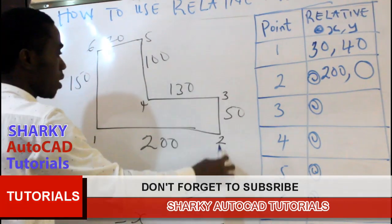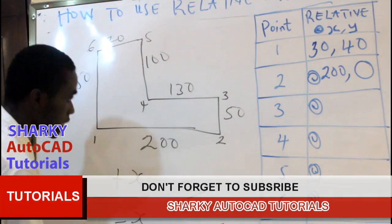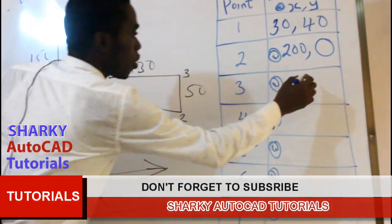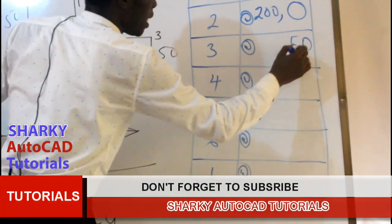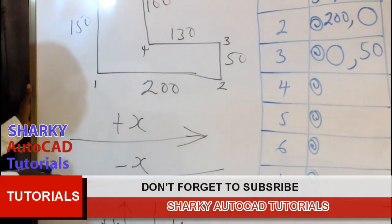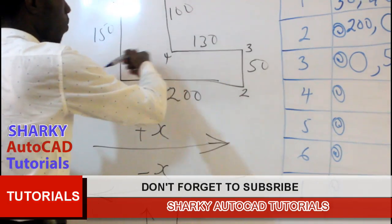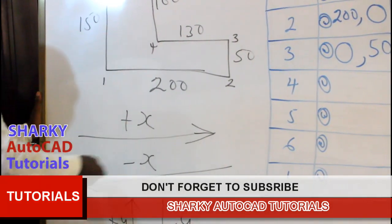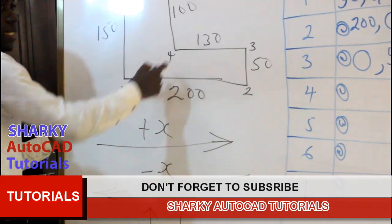At point 3, what direction is this? It is positive y, and the distance is 50. So you write 50 here, and then no x, so x is 0. And then at point 4, what direction is this? It is negative x, and the distance is 130.